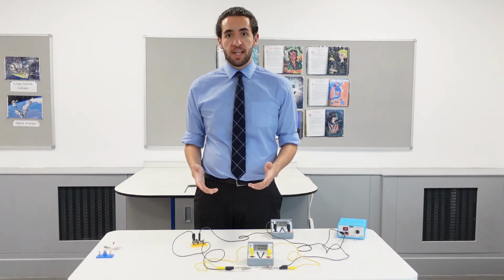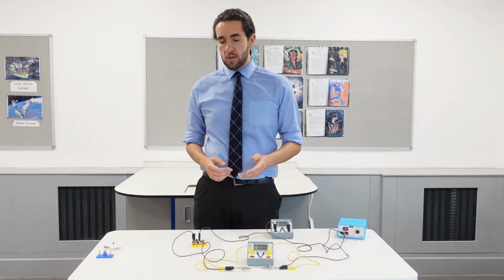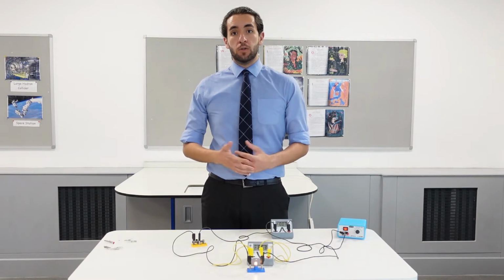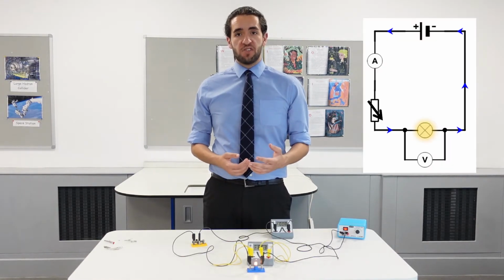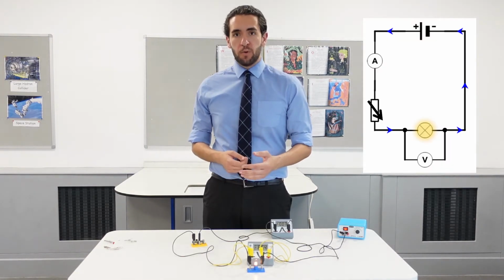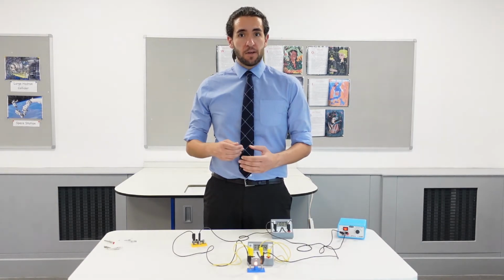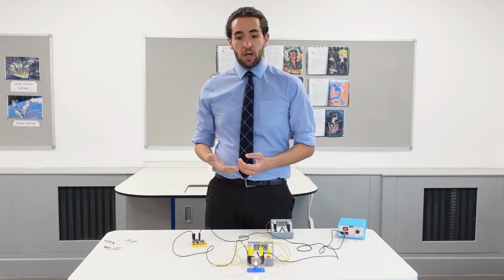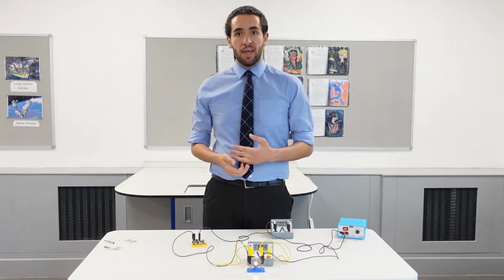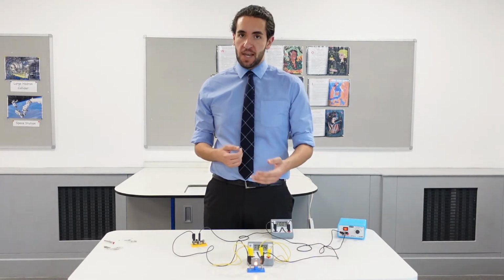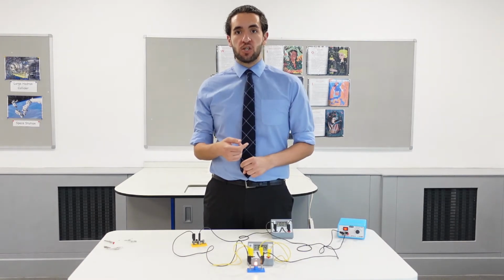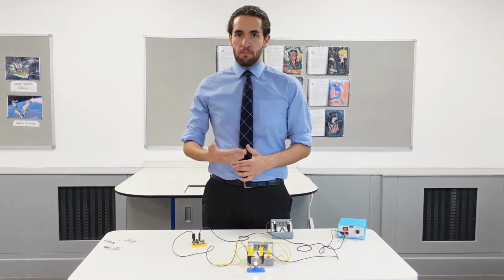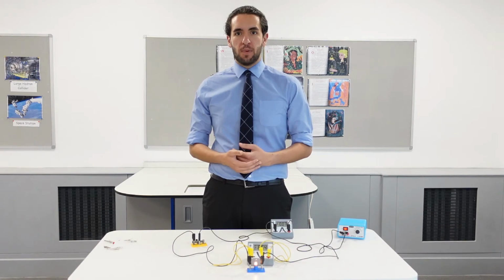Let's repeat this process now, but instead of a fixed resistor, I'm going to have a filament lamp. You'll notice that all I've done is swap my fixed resistor and crocodile clips for the filament lamp. And I'm going to do exactly the same thing again. I'll be adjusting my variable resistor until the potential difference across the lamp is 1 volt, 2 volts, up to 10. Then I'll swap my connections and I'll go from -1, -2 volts, all the way down to -10 volts. And for every one of those, I'll be recording the current that flows through the lamp.